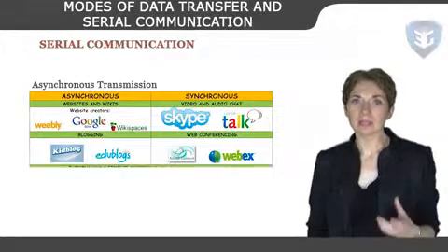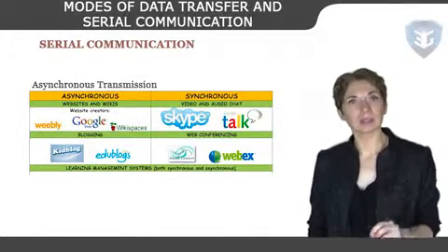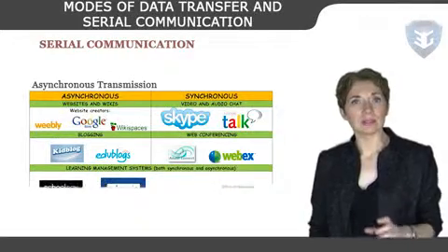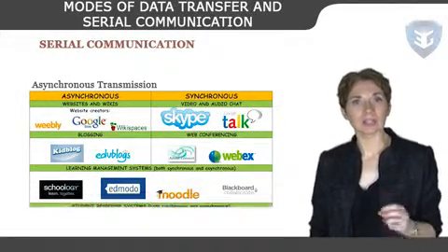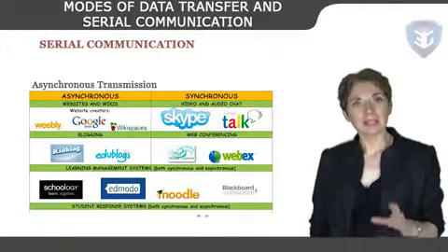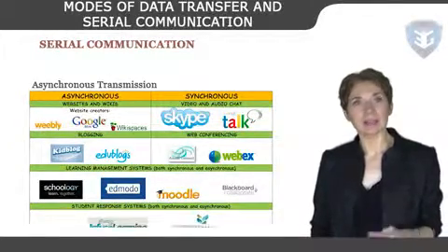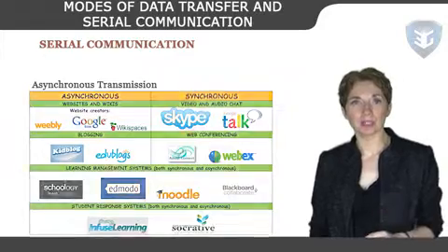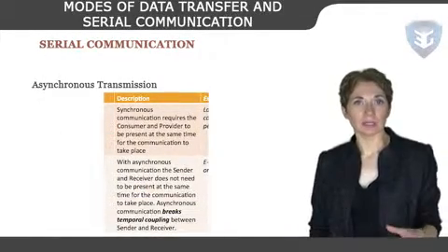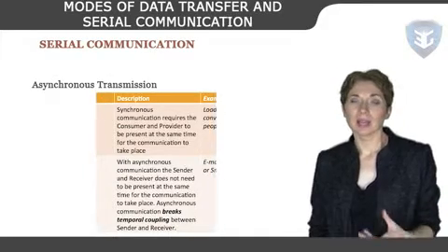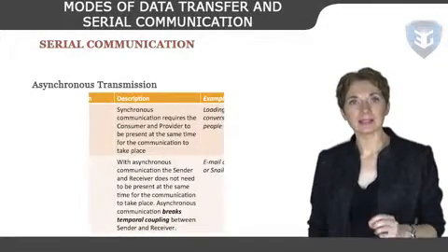This means that the receiver must decide where to look in the signal stream to find ones and zeros, and decide for itself where each individual bit stops and starts. This information is not in the data in the signal sent from the transmitting unit. Most communications between devices within computers and between computers and external devices are asynchronous.